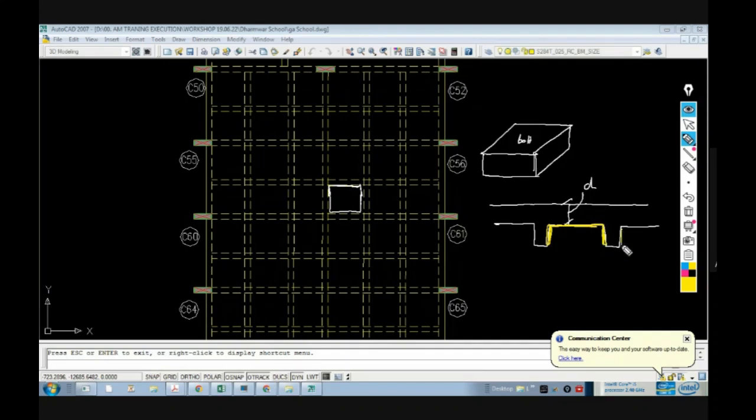So I will keep each and every box here side by side. Whenever I have this box, the bottom is done separately. This bottom will remain for the beam. Have all of you visited any construction site? Then you will know this bottom. Yes sir. So the bottom is kept first, then these boxes are arranged, and then the propping is done for everything. That is how everything is done. And then putting the reinforcement.